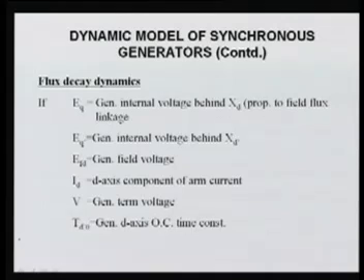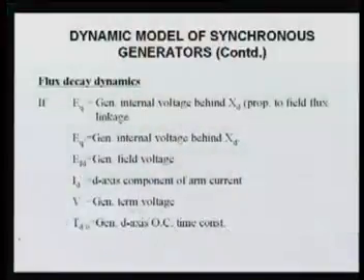Now come to the flux decay dynamics, which means detailed representation of the machine itself. You know, there are two fluxes. One is the rotor flux, another is the armature flux. Both are rotating in the air gap at the synchronous speed, and the torque, that is electrical power, is produced due to the interaction of these two fluxes. So the flux decay dynamics is used in most of the cases.